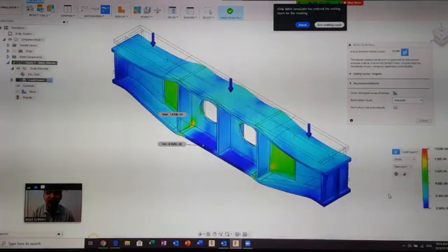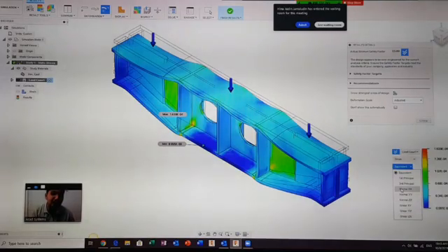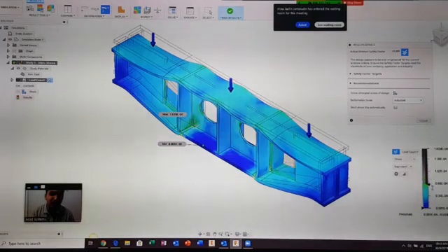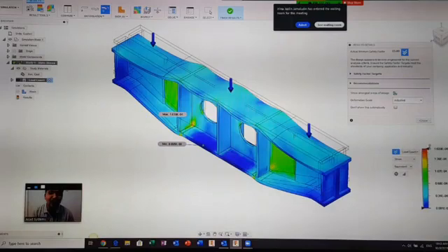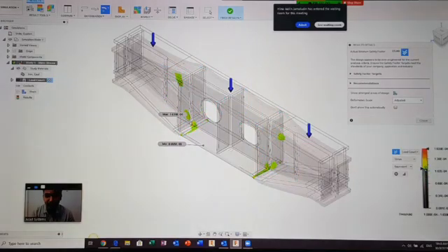And the last one you can have is the strain value, which has equivalent, first principal, third principal, normal and shear. This result you can customize here. You can see when I'm dragging this, you can visualize it inside your design window here.